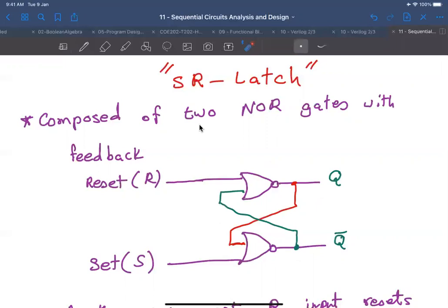So we have a reset input, which is R here, and Q. My bit that I want to store is in Q. This output here is my bit, and it can be a 0 or a 1. This other output is just repeated: it's the complement of Q, so it doesn't add information. It's not an extra bit, just the complement of this bit, and it comes for free because of the design of the latch.